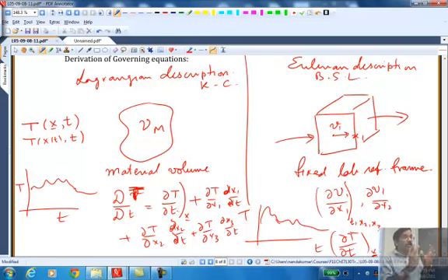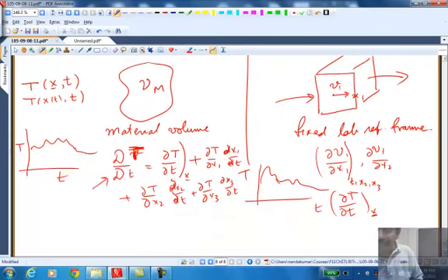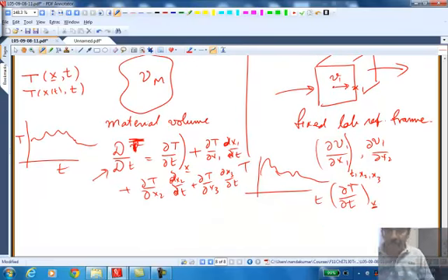So that total derivative, that chart that he gives me, and if I take the derivative of that chart, I am actually capturing this entire information. And this is called a substantial derivative, Lagrangian derivative, total derivative. There are different names given for it in different books. But that contains the information not only of temperature change with time, but temperature change with position. And what is dx1/dt? The velocity of the skydiver. dx1/dt is the rate of change of position with respect to time, right?